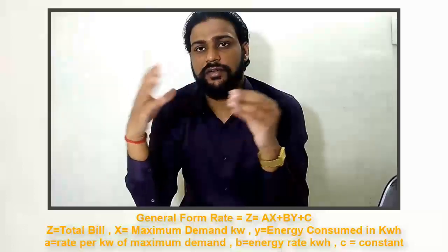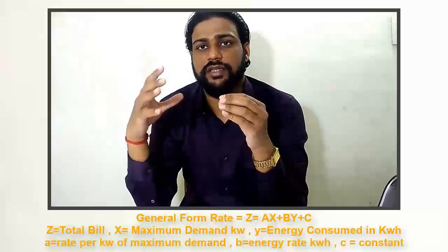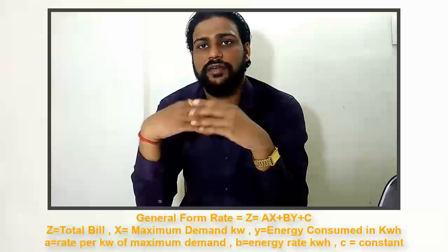Also, when you are throwing it directly on the turbine blades, it is known as impulse, and when you are making it flow in a large quantity and expand on its own, it's known as reaction. So there are two kinds of turbines, the impulse turbine and the reaction turbine. And again, you will need to condense this steam so that it can be fed back to the boiler for heating. That is done as part of the condenser process.